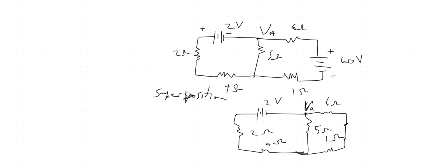For the 2 volts, for the first loop, then what? Would the 2 volts and the 4 volts be in parallel first? No, what I'm saying is you could just do a loop analysis with the 2 and the 4 ohm and the 5 ohm with the 2-volt source in loop 1. Right? So what's happening there? This is going to be 2 because it's coming out. We're going this way. No, we're not coming out of the positive, we're coming out of the negative. So we're going to say 2 instead of -2, right?